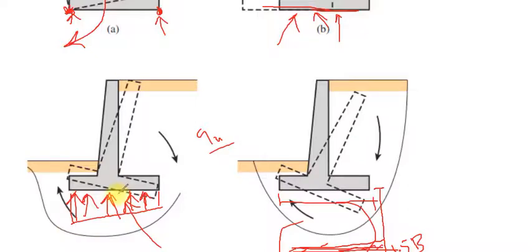The soil under the base of the retaining wall may not be sufficient to carry the vertical loads coming from the retaining wall. So we have to compute the ultimate bearing capacity of the soil, by the different equations that we have learned in the first course, and get the safety factor against the applied pressure. The load coming from the retaining wall causes non-uniform distribution under the base of the